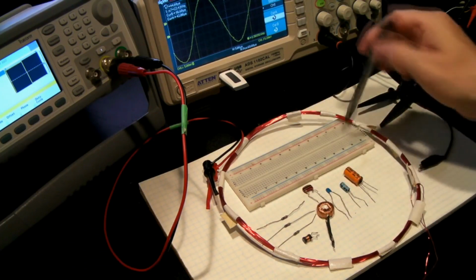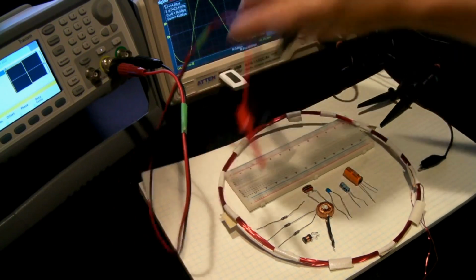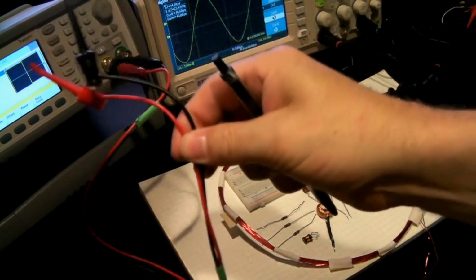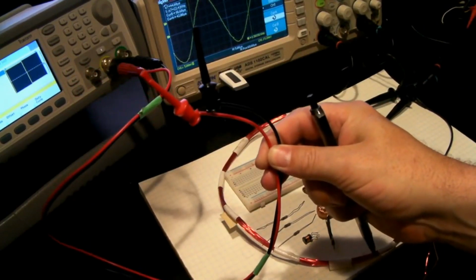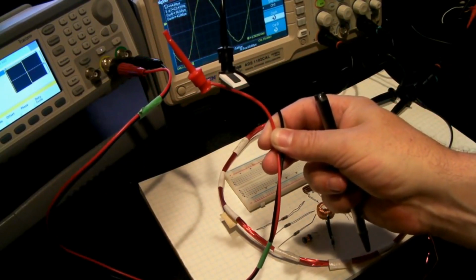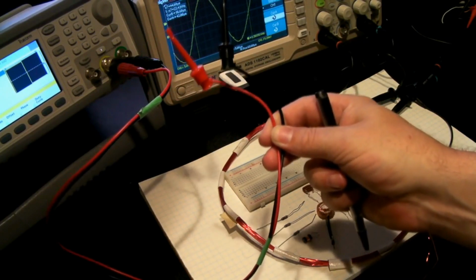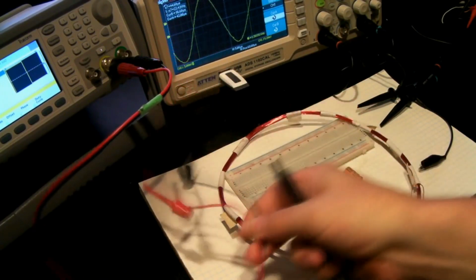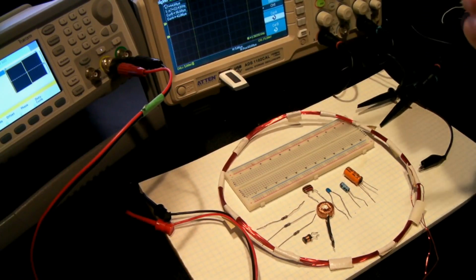So given this and a simple breadboard, I'm going to use a lead that I just made up to come out from the Agilent waveform generator. It's going to provide me the various square waves that I'm going to use to verify the inductor and the capacitor values through timing, using the oscilloscope to do the measuring. So right now I don't have anything hooked up, so I'm starting from scratch so that you can see everything we're doing.